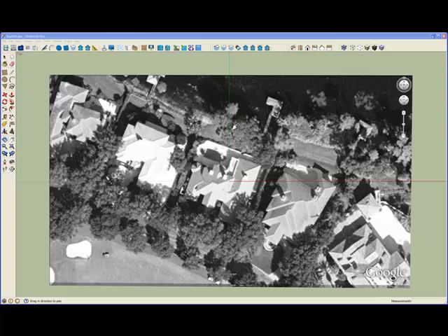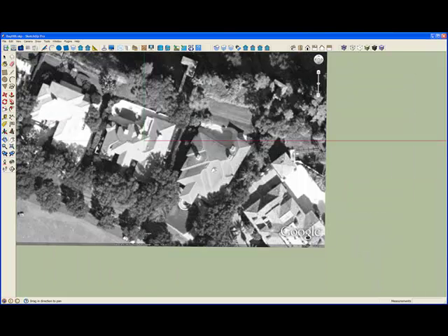This is a continuation of the GeoSketch Tools video for the Pitched Roof Tool. In this case we have an image that we imported from Google Earth, and we'll scroll over to look at this particular house. We'll select our roof parameters. We're going to build a hip roof, and we'll use our construction profile of the ridge, because we'll use the center line of the ridge to define the profile, and our construction plane will be at the foot.